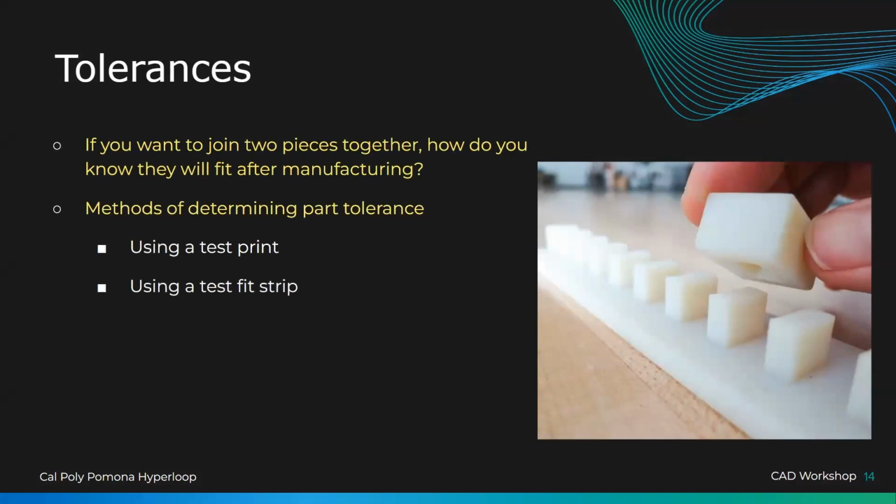So that's important for manufacturing because, as we know, manufacturing is not precise. There's always going to be some error involved. Especially with stuff like 3D printing, all materials, if you don't know, have a coefficient of thermal expansion. So if you're making a cast part or a 3D printed part, the part that comes out is going to be a little bit smaller than the dimensions you planned for if you have not accounted for that in your planning.